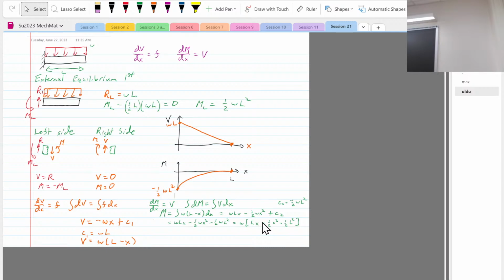So transverse shear stresses are going to be 0 at the top or the bottom, because A prime is equal to 0. There's no area over which it's acting, so it's equal to 0. Okay, I got it.